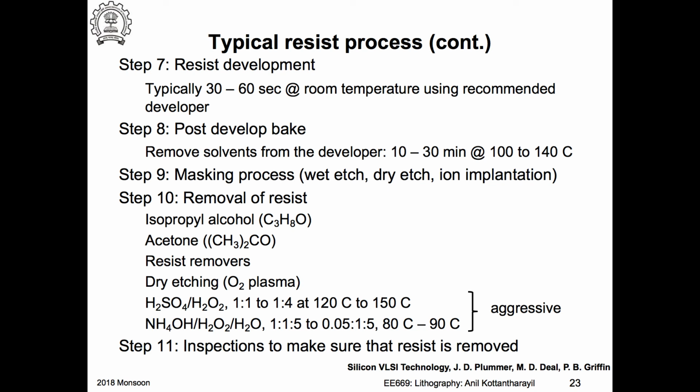this is another one: ammonium hydroxide, hydrogen peroxide mixture. These are quite aggressive chemicals. But then of course one very important thing that students many a time don't do is to inspect these wafers to make sure that the photoresist has been removed. Very, very important process.